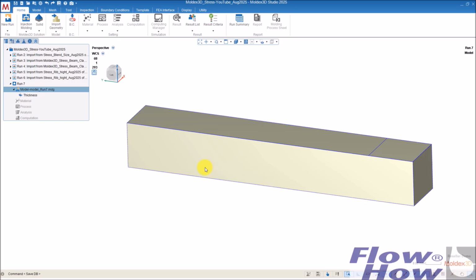Moldex Stress has some different possibilities. There's a normal FEM analysis where you bend a beam or put on some load with some constraints, boundary conditions. And then the other thing is you have annealing, where you see the long time effect of putting on heat. But in this case, it's only the normal strength calculation.